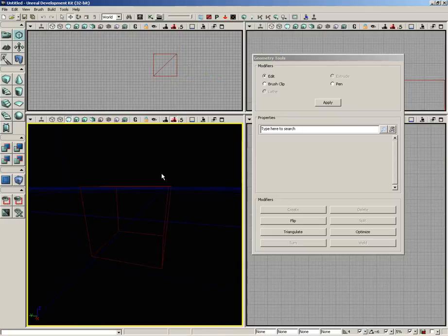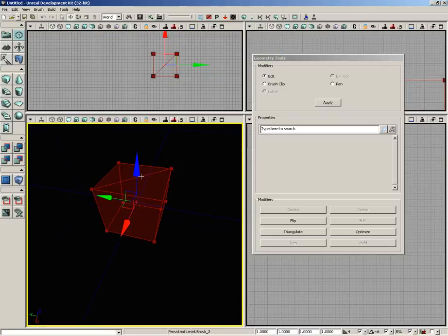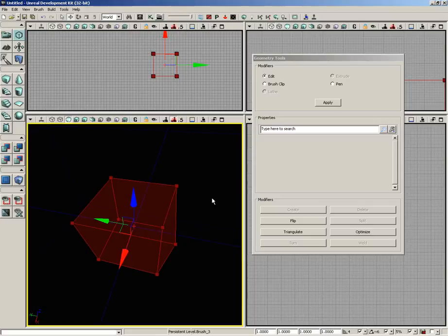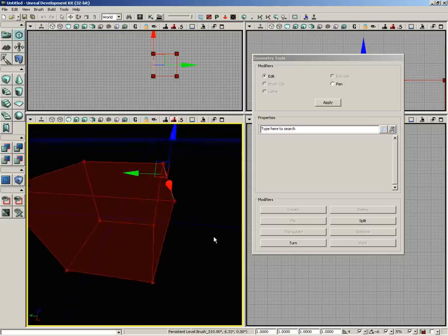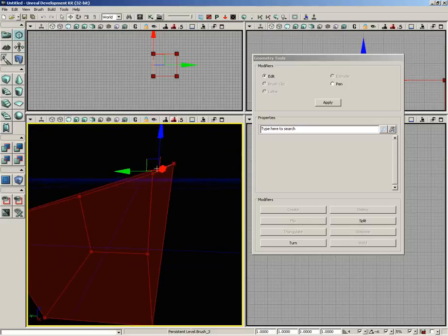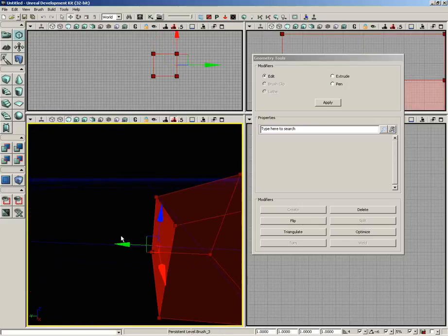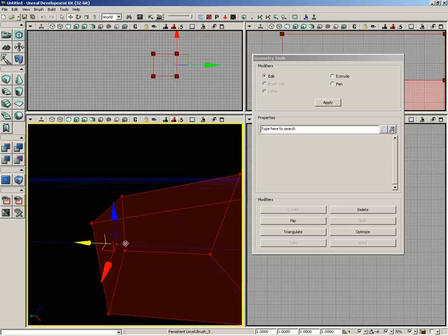And if you didn't like that triangle edge, if you just had to absolutely get rid of that, you can select your brush. So notice I deselected, reselected the brush itself, and we can click on the Optimize button, and that'll take out any unnecessary edges. So back over in Edit Mode, we can click on edges and manipulate those as well. So I can pull an edge up. We can click on Faces, and I can manipulate those.